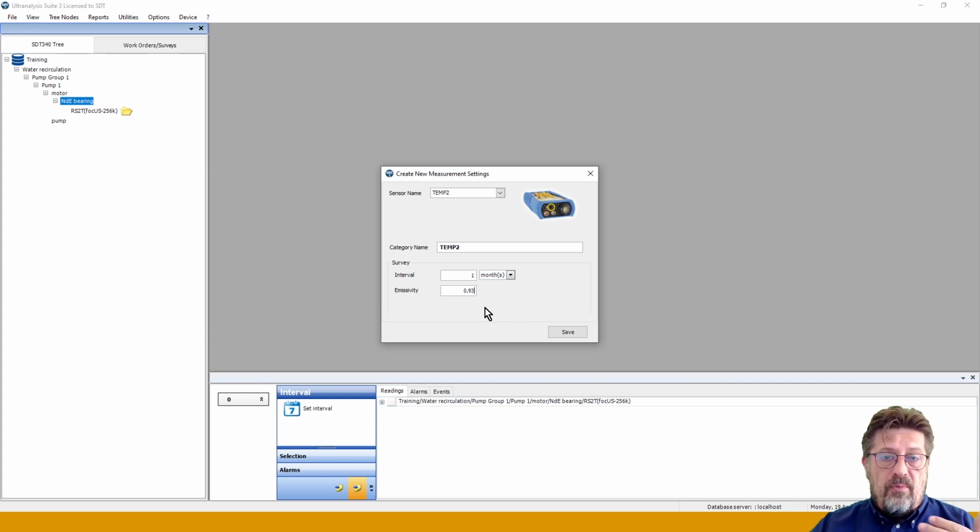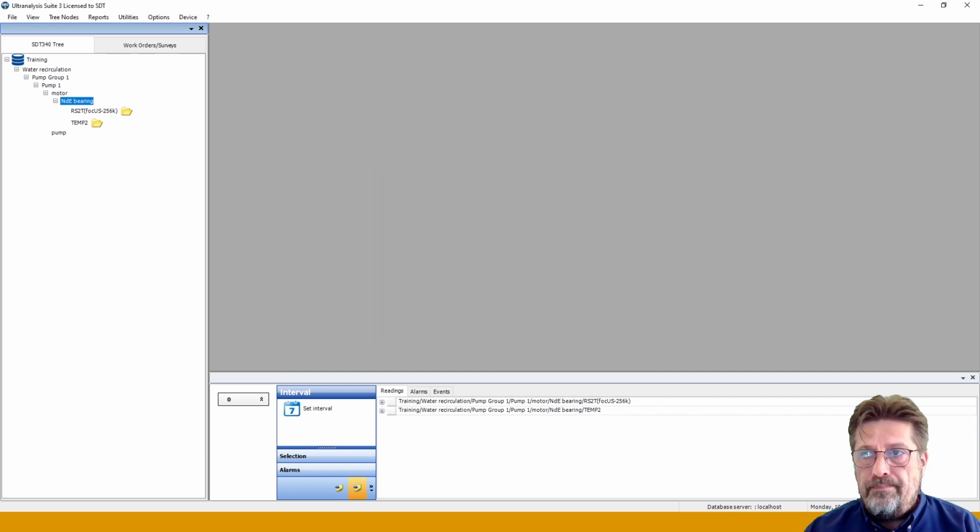If you leave 1, your trending will be fine. It will show you increase, decrease, or staying the same. But if you want to have a correct temperature, please get informed about the emissivity of that particular surface. Put the right emissivity, and you will have the right thing there.